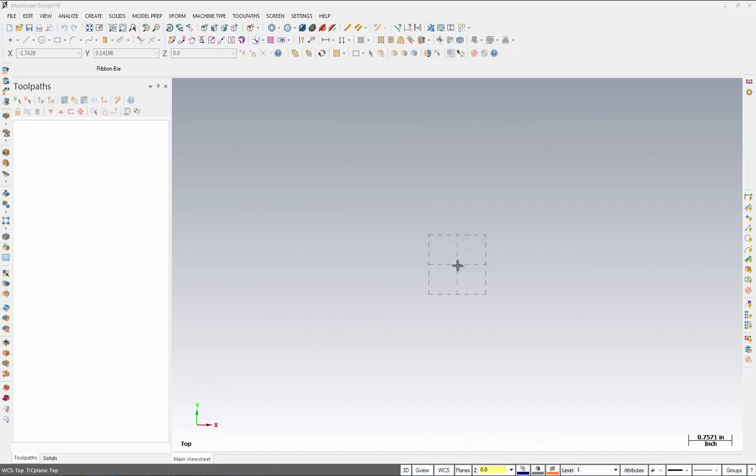As you saw on the previous screen, that is the blueprint and the CAD drawing that we're going to create. As you can see also, I've already established my grid under grid settings and have changed my default color to blue. I was able to do this by following step number 1, setting up the graphic user interface. I'm going to proceed with step number 2, which is creating a rectangle.